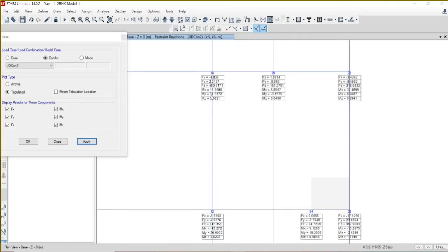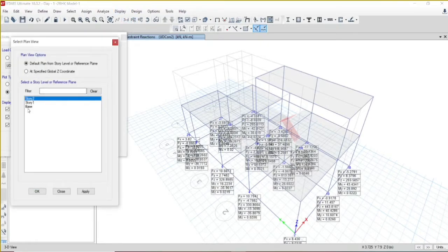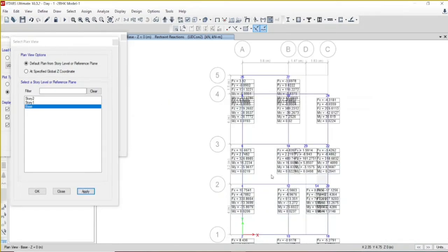You can see the moment which is considerable. You are having 34 and 16. So in X direction you are having 37. So these are the considerable reactions which you can find the critical section. And if you are looking into the plan, rest of the area you can see much lesser. FZ due to all critical is 2 times reduction.